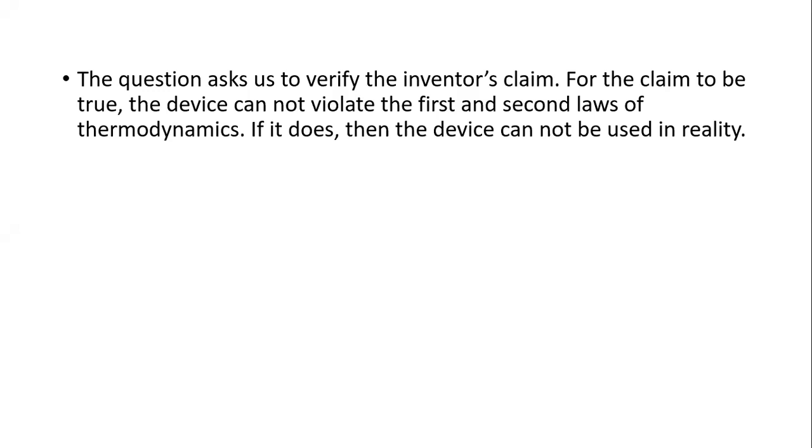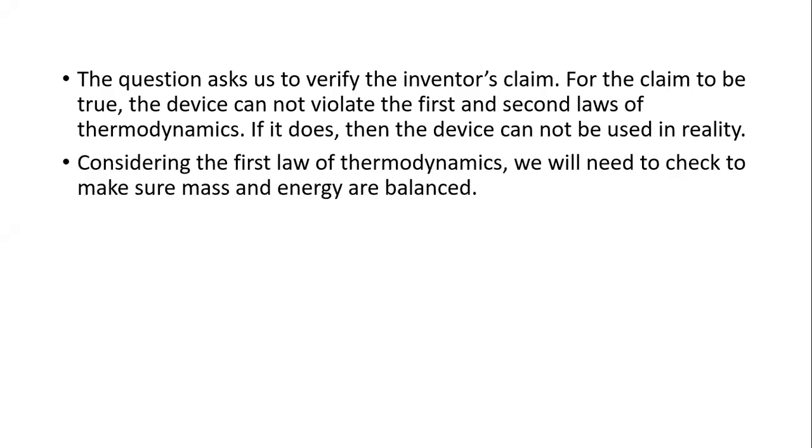For the claim to be true, the device should not violate any of the laws of thermodynamics we've looked at so far, so both the first and second laws. If it violates any of the laws, then it can't be something that would actually work in reality. So if we consider the first law of thermodynamics, we need to check to make sure that mass and energy are balanced. So we know that M1, what is coming in, will be equal to the sum of the outlet streams, that's M2 and M3.